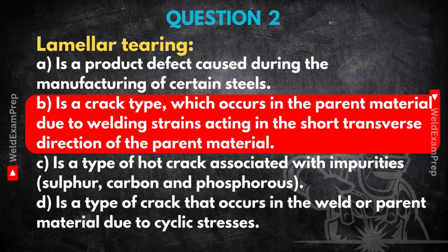You get these characteristic step-like cracks. And what's really insidious sometimes is that the welding just exposes a weakness that was already in the parent material. It changes how you think about prevention. It's not just about the weld itself, but the plate material too.